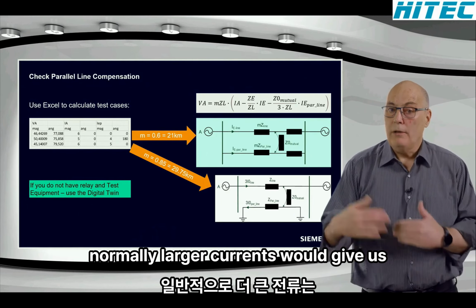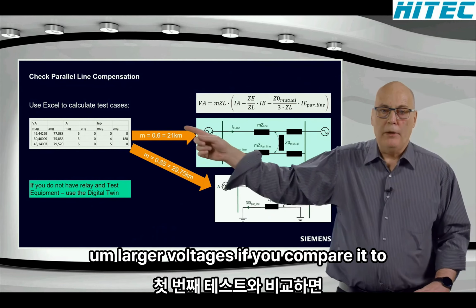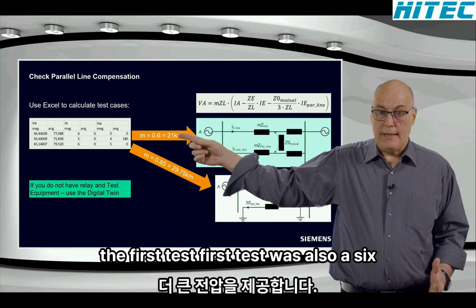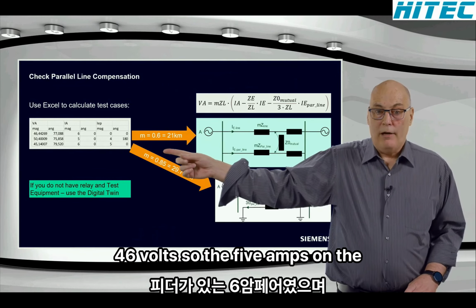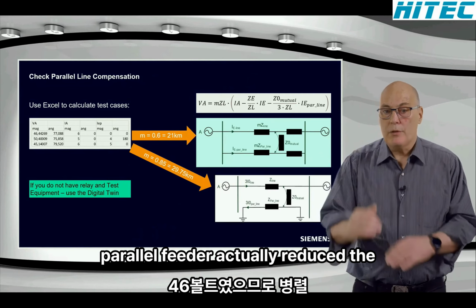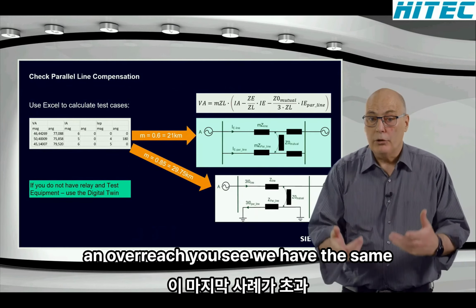Although it's a larger current, normally larger currents would give us larger voltages. If you compare it to the first test, which was also with 6 amps on the protected feeder, it was 46 volts. So the 5 amps on the parallel feeder actually reduced the voltage. That's what we expect, and that's the risk that this final case can give you an overreach.